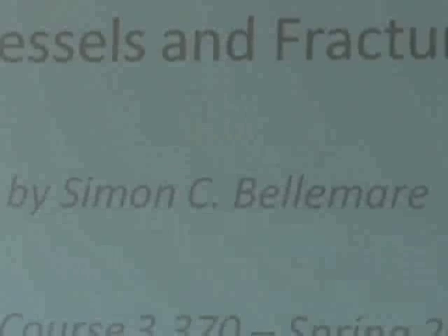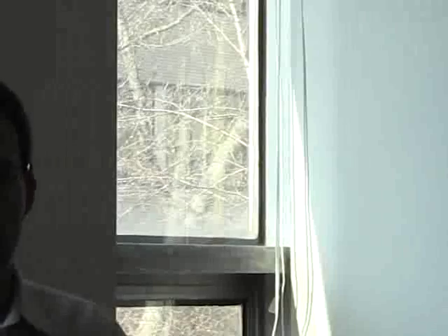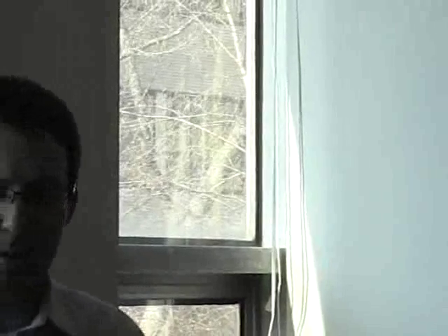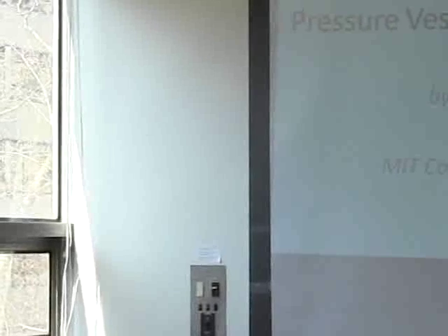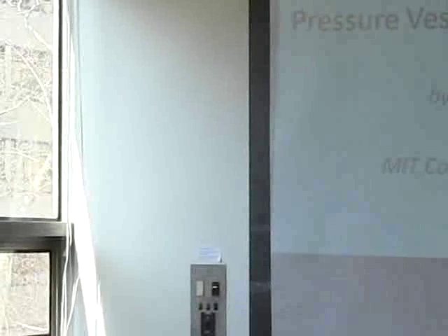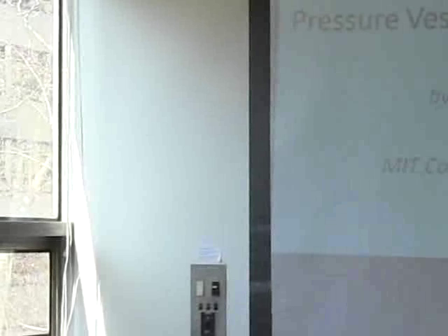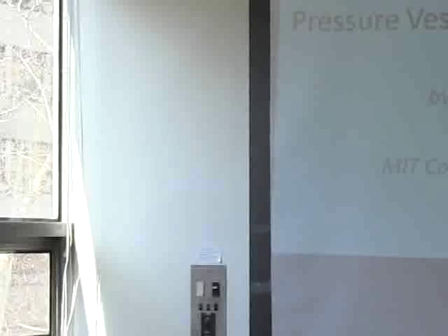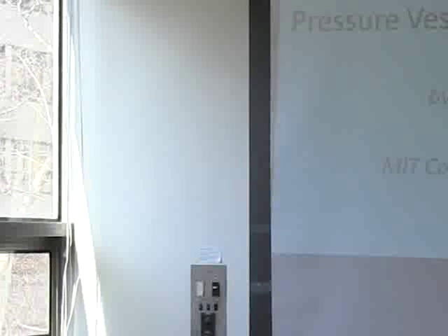Two main things. First, we'll look at a relatively thick wall where we use the K concept that we talked about. And then I mentioned to you R curves when we were talking about whether the plastic zone is small enough to do the analysis. So we'll do a case that's actually probably the most common with pressure vessels, where you have a thin wall, and when you start a crack, you really tear it, as opposed to popping the whole fracture. So it will propagate as a crack, but it's not going to be a rapid propagation.